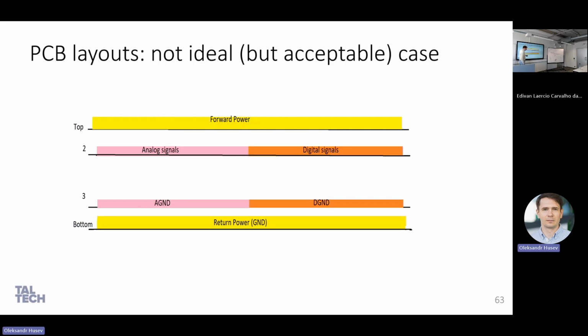In one case you just drill the whole PCB, which is easier. In this case, it's not easy. Even at this stage, if you do drills here, it's also more expensive. But I read in some material from our team that for signals in inner layers, you should use these blind vias, even though it's more expensive. It's not that it should. If you are ready to pay for that, fine.